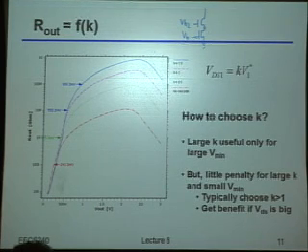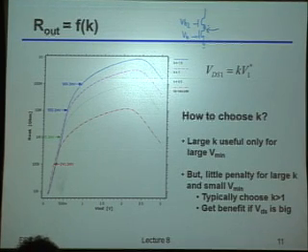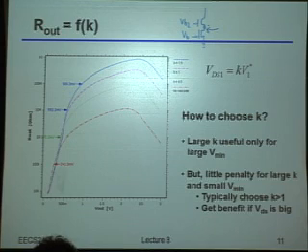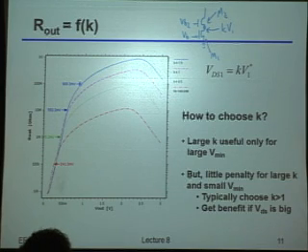If I look at that internal node there, how should I choose the bias for that internal node? Let me label that device as M1, and this device is M2. How should I choose the bias of that intermediate node relative to the V star of the bottom device?